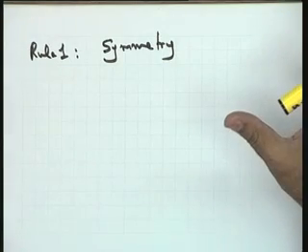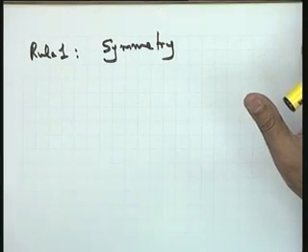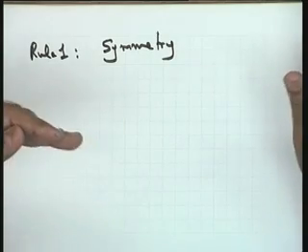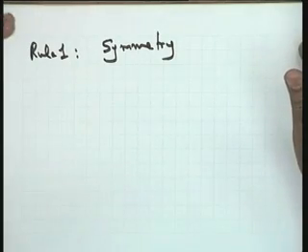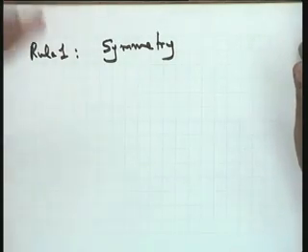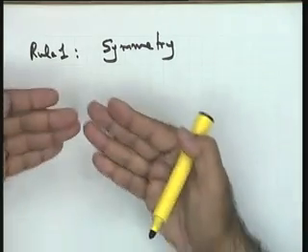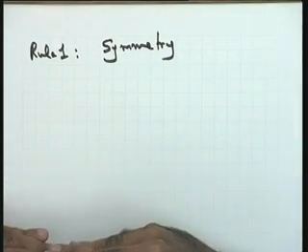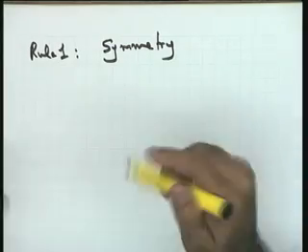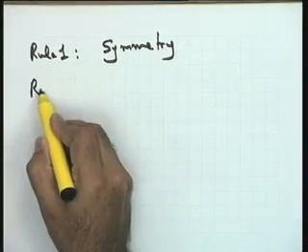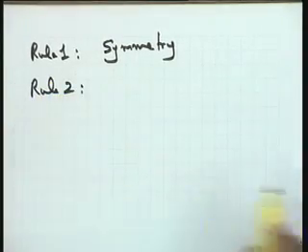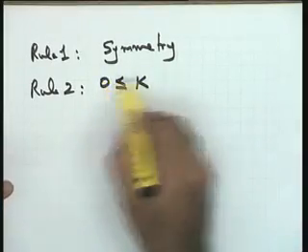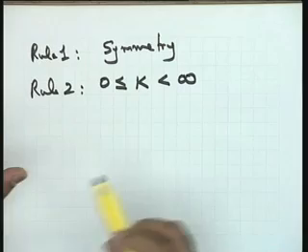Then and only then will your characteristic equation have real coefficients. So if you are making the upper part of the root locus plot very accurately, do not worry about the lower part; you simply take the mirror image of that, because it is going to be symmetrical with respect to the real axis. Okay? Rule 1.